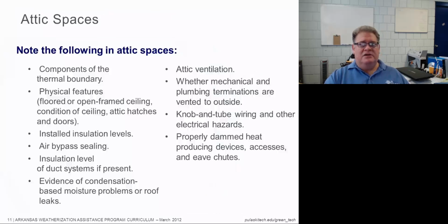Okay, so when you get up into the attic, what you want to look for are what are the components of the thermal boundary? Do we have sheetrock and top plates that are making up a good continuous thermal boundary? What are the physical features of the attic? Is it open floored, meaning that we have exposed joists everywhere, or is it a floored space? Is it cathedral ceiling? Is it a partial cathedral ceiling with a flat top? Do we have insulation at every different level? And is that insulation relatively the same? Did they find the bypasses up there, and did they seal them? Okay.